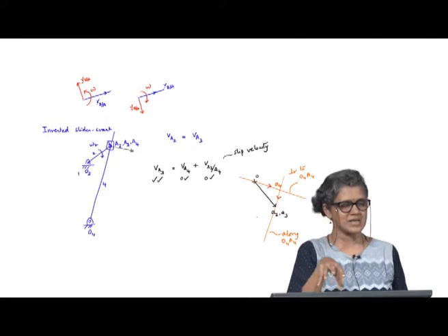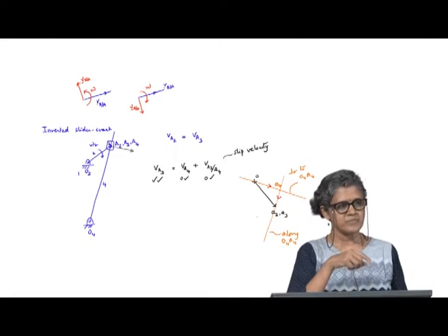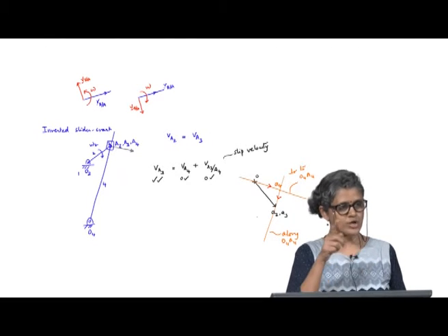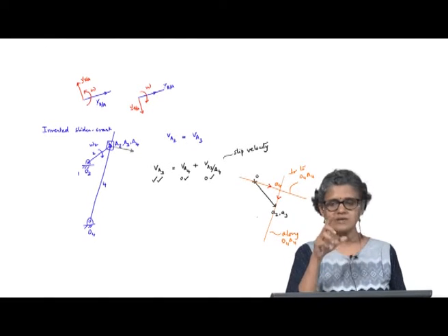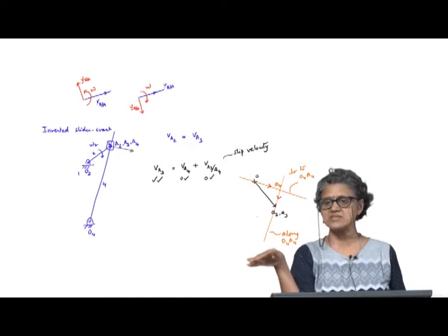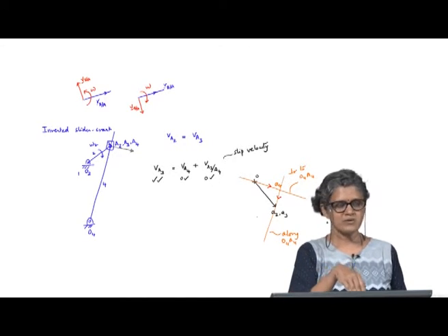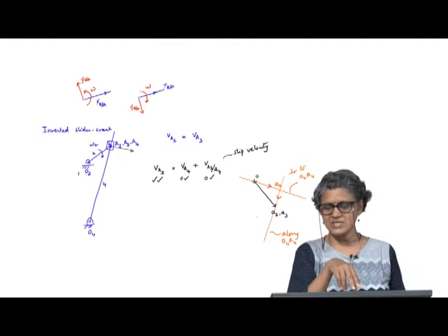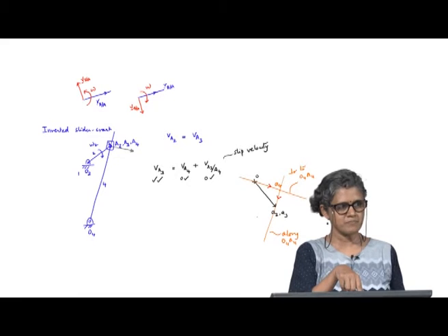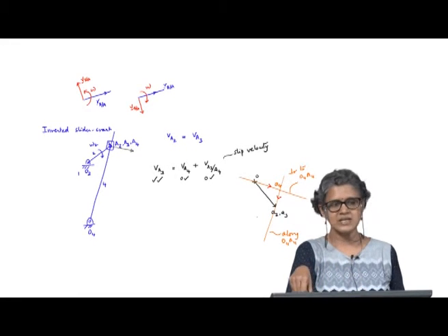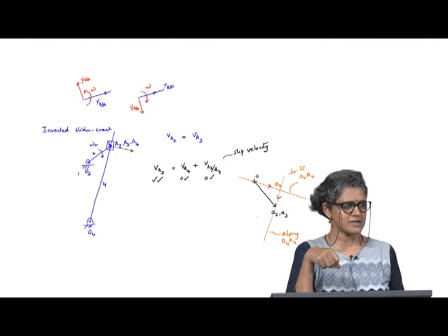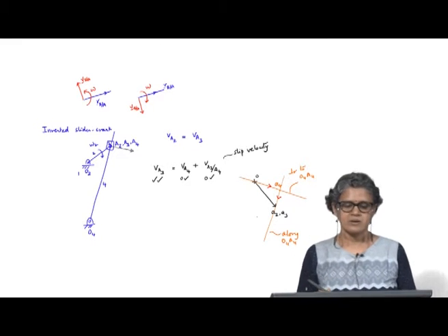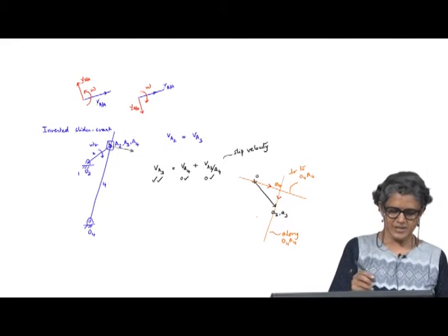when we do the acceleration analysis, because when you have a sliding joint on a rotating path. Okay. Earlier when we looked at the slider crank, the path remains fixed. But when you are looking at inverted slider cranks, you are looking at a path which is also rotating, and in those cases the Coriolis acceleration will come into play, and that Coriolis acceleration is directly related to the slip velocity that you find from the velocity diagram. Okay. So, this is the case of the inverted slider crank.